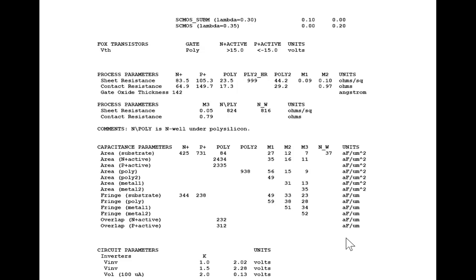Remember, we asked the question, is that 1.5 femtofarads that you have for that gate capacitance of a transistor negligible? Well, our conclusion was no. Why was it not negligible? It affected the rise and fall times. So you can work backwards and say, if I could measure the rise and fall times, could I infer what that capacitance was? The answer is yes. There are a lot of clever techniques for measuring even very small capacitors, not necessarily directly. The other way you do it is you make it big. If you make the area big, then you have something you can measure, and then you can scale it down.